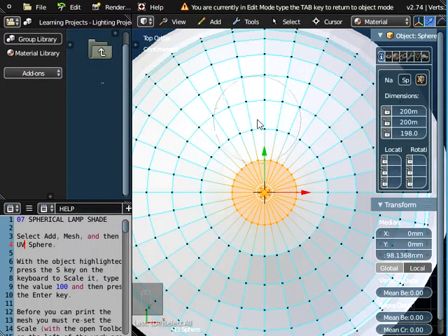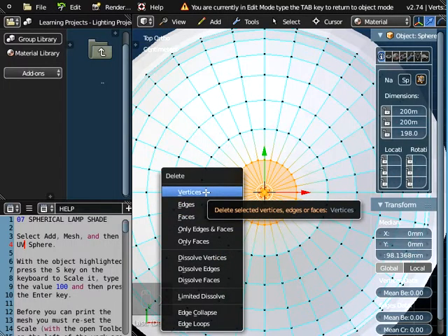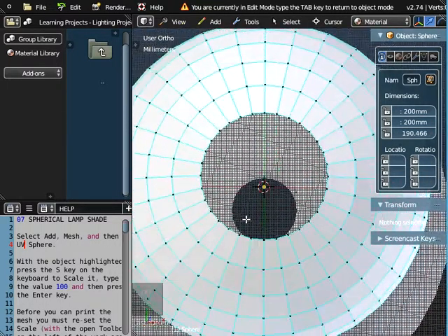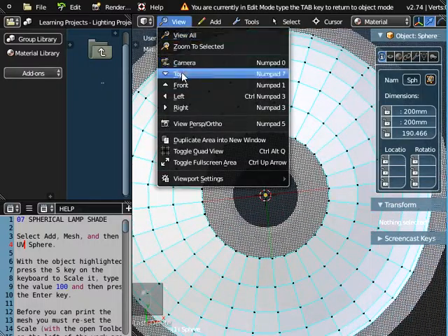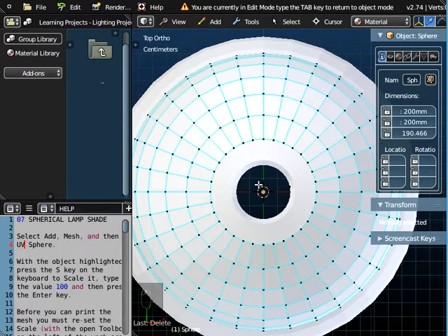Now to cancel the circle and then to complete the deletion, I must press the escape key on the keyboard. You must press escape on the keyboard to get rid of that. Now we want to delete the inner part of the object, so it's X on the keyboard and delete the vertices. Now when I delete the vertices, notice the size of the hole that I get. View it from the top again. Now that's actually a bigger hole than the one at the bottom, so I've actually deleted more than I wanted to, really.